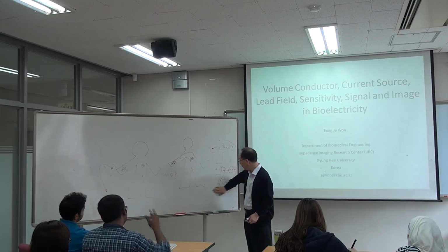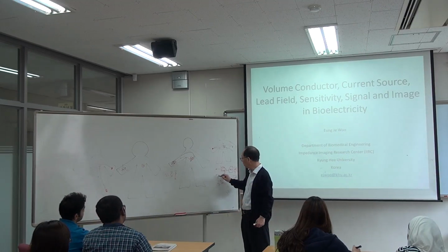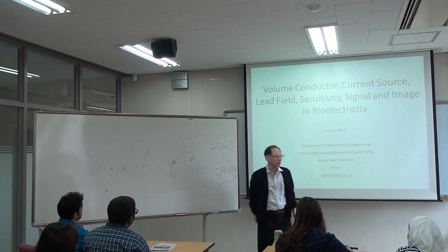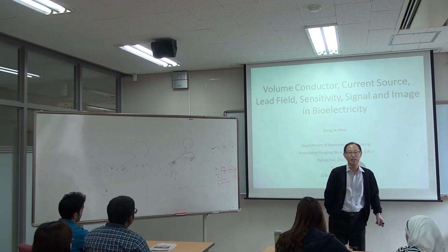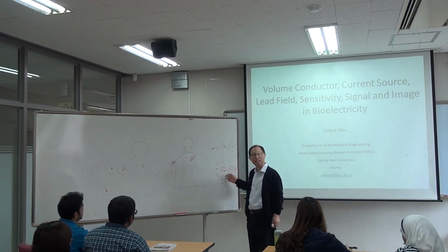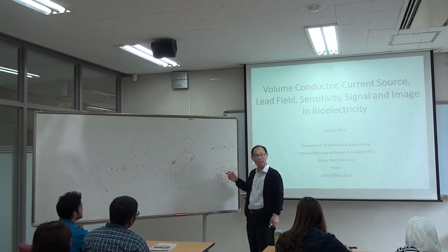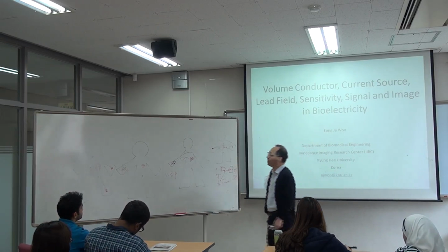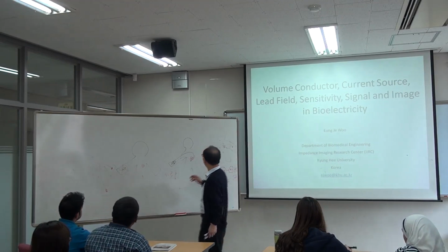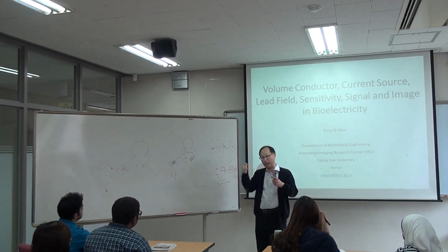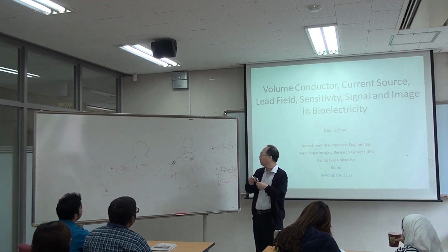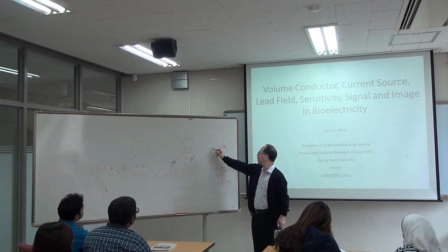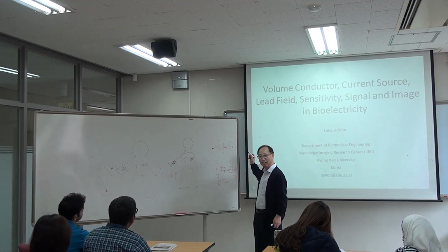If we want a single-ended voltage measurement, then you can just do this. Then you can just measure ECG using the 2 electrodes. But in this case, you have more noise. You have higher noise for instrumentation reasons, for circuit design reasons. So in this case, the lead vector through the heart is along this direction, right? Because current is passing horizontally. Agree?